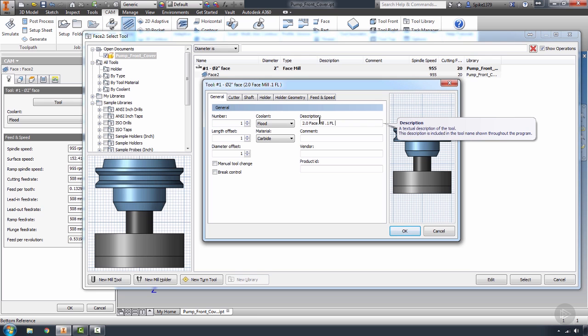This is a reminder to me how I would like to use the tool, and at the same time what I can do is set up a standard for my shop to be able to use as a blanket statement. This insert cutter only cuts 100 thousandths max in any given material that it's used for. You'll have to create your own standard operating procedures for that. But a big ticket item that I like to do is I like to go ahead and add the material.